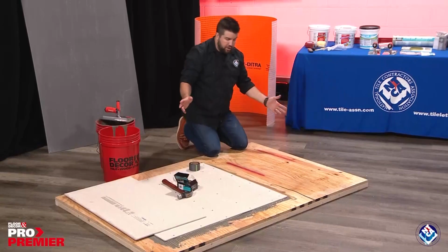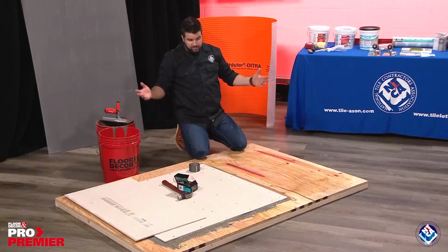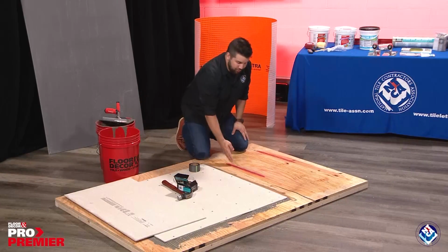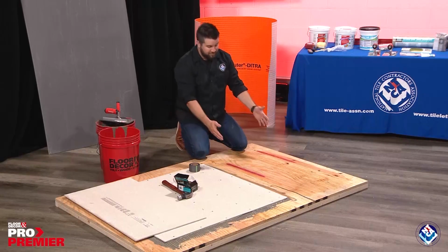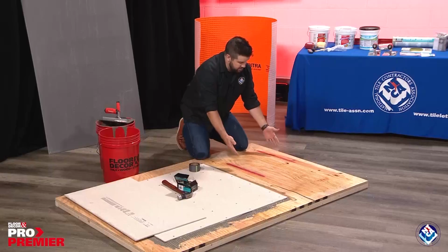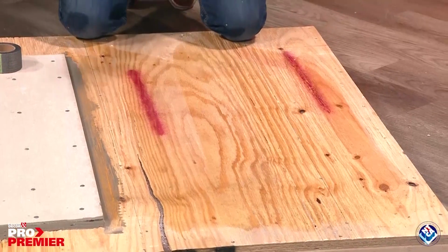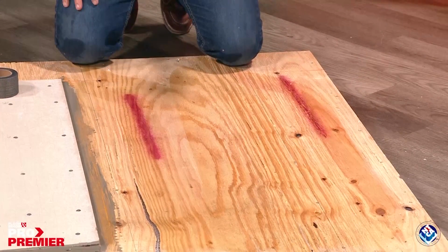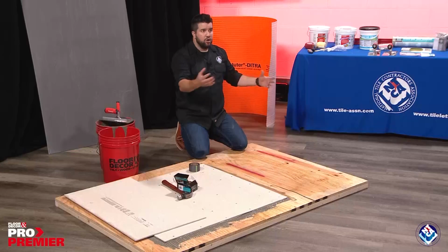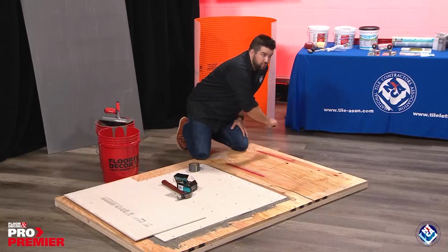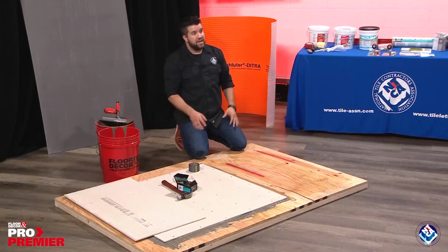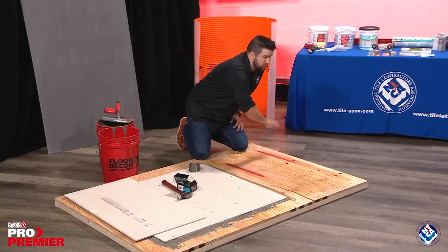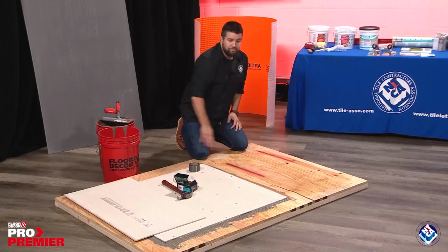We've still got one problem that I'm not going to be able to fix today because I don't have all my tools with me, but we've got paint here on the floor. It came like this from the box store, and we would want to address this. We've all seen on jobs, whether it's new construction or renovation, that paint overspray the painter will always leave us, 6 inches around the perimeter. We always want to address that. We want to take a belt sander and sand that off.